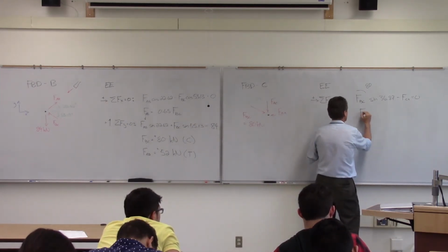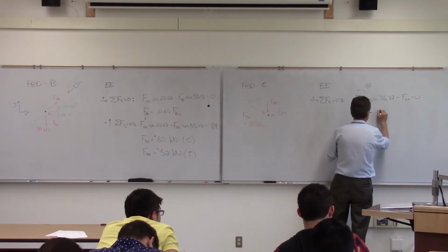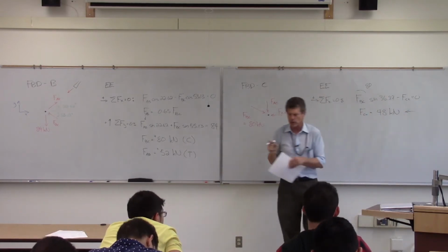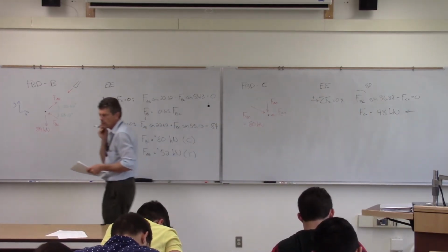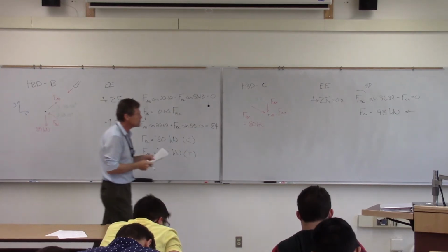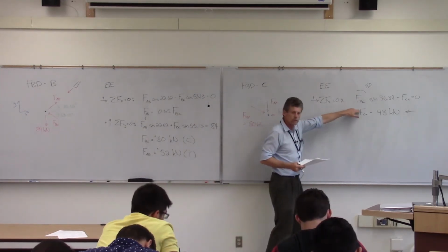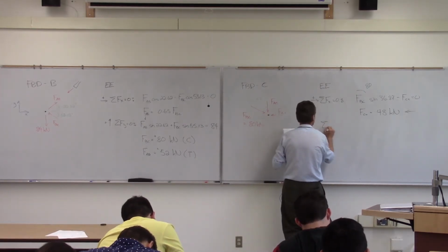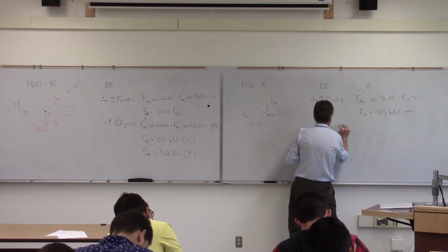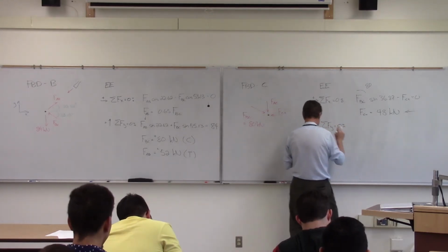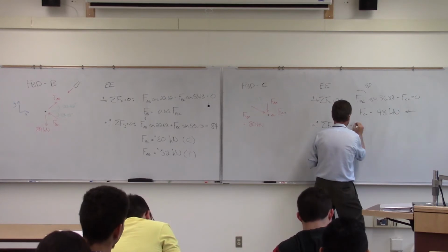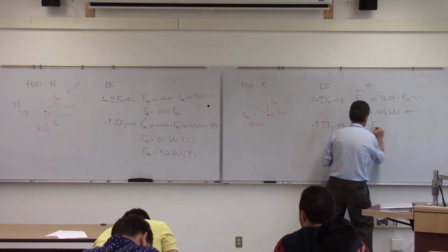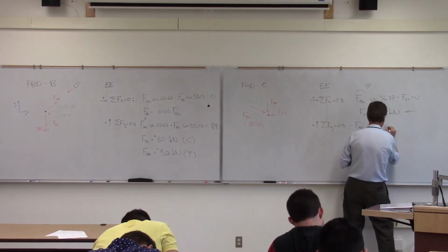But F Cx will then equal, now since it's a support force, I can't report that as compression or tension, so I actually have to report a direction. And since I know it's horizontal, it's going to be pretty easy there. But again, this is a vector. We need to report it as a vector. And then the other piece then, and this is why I say pay attention to your signs. FAC is going to be negative. FBC is also negative, and cosine of that angle.